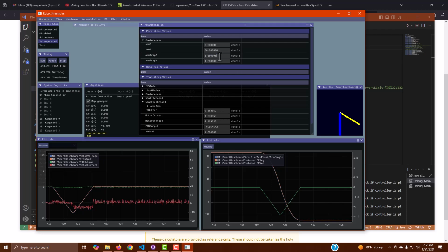We could also go a lot faster if we wanted to. And again, the limit on how fast you could go on the real robot may change. The simulation should be close, but values in simulation should just be a starting point for the real robot, but they should be good starting points. Now that 1.8 acceleration, we can change a good bit. You can make it go pretty fast, but there is a limit to the velocity that you can run. And this 1.8 is pretty close.